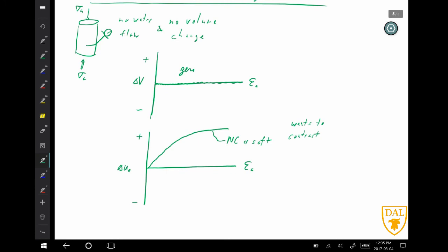Okay, now think about the dense sand. First it contracted a bit and then it dilated. Okay, and so if it's not allowed again to change any water in the system, all the voids remain soft. So first it has a tendency to contract. It's pushing on the water, okay, causing an increase in pore pressure. And then very quickly, the soils have a tendency to want to dilate, right? Find a more open structure. And in a sense, it starts to pull on the water in the voids as it has a tendency to want to dilate, but it cannot.